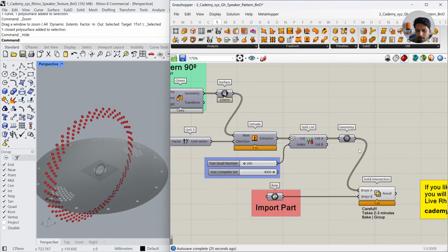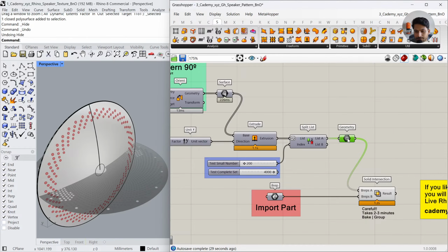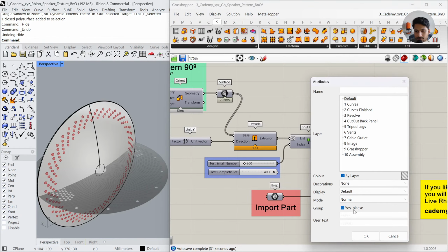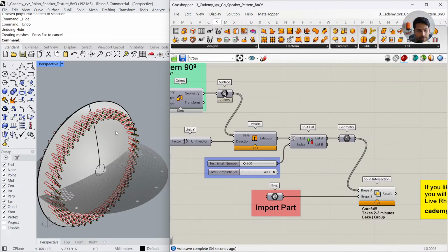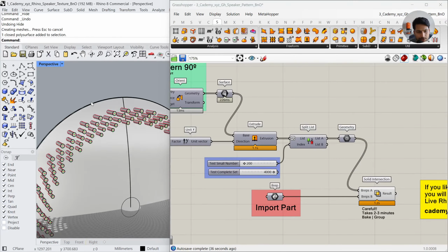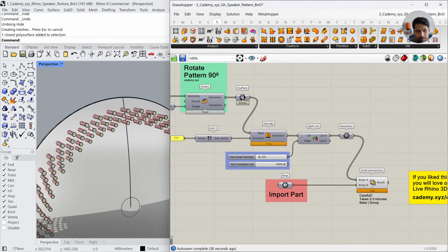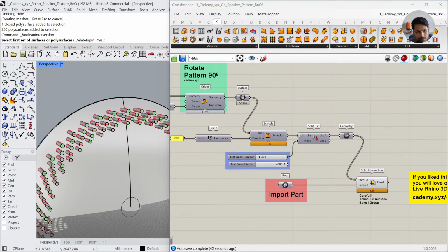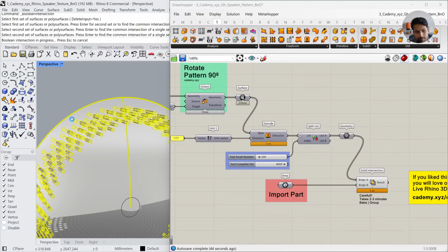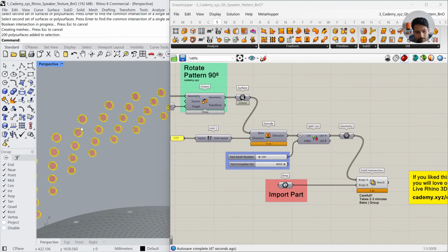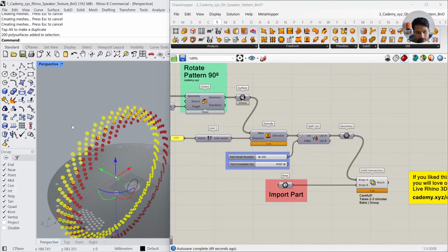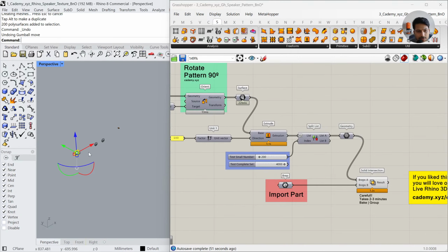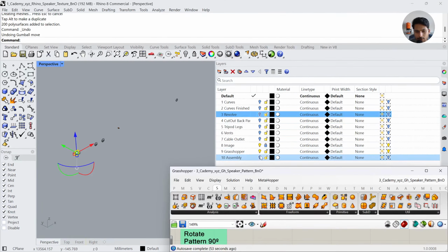Okay, we could have also extruded the geometries in Rhino. Okay. And then perform Boolean intersection in Rhino. So it's a bit faster. Solid operations, Boolean intersection between this and this geometry. So it's going to give us the remaining intersecting parts. Okay. So once all of this is done, you can go to this next layer called assembly.